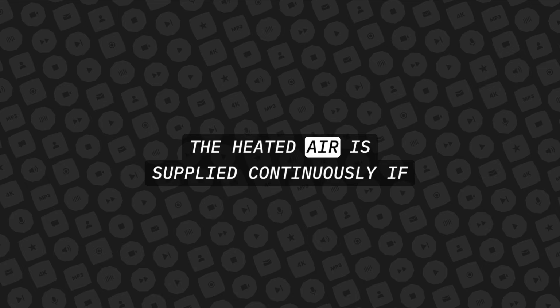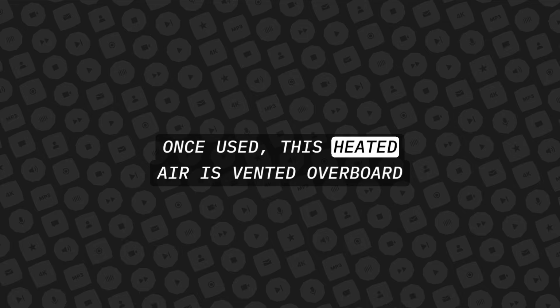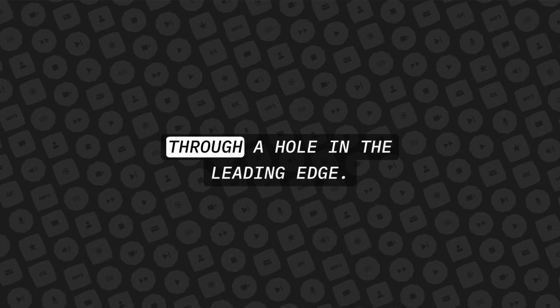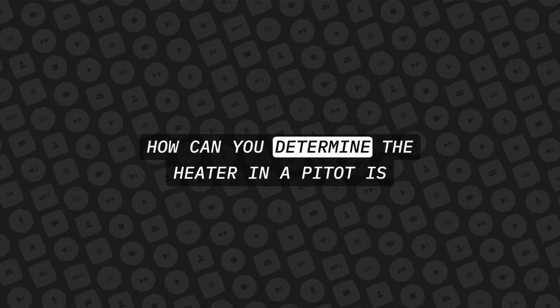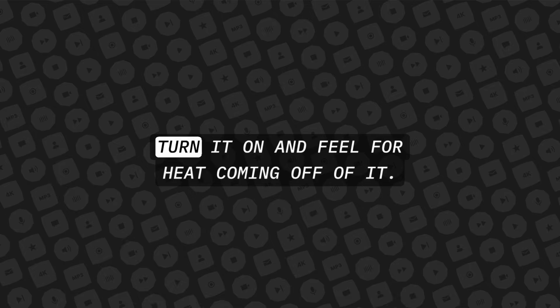The heated air is supplied continuously if the anti-icing system is turned on. Once used, this heated air is vented overboard through a hole in the leading edge. How can you determine the heater in a pitot is working? Turn it on and feel for heat coming off of it.